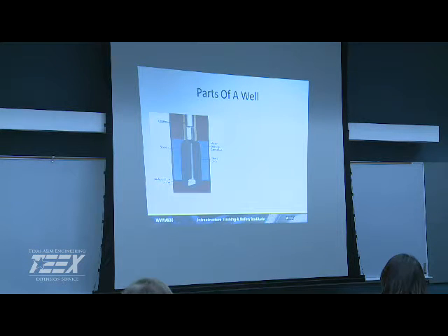We do need to have the casing sealed well. When we talk about wellhead protection, we got to not only protect on the surface of the ground, but we also need to make sure that our casing is intact, is sealed properly, things like that. And of course, in some areas you can have a couple hundred foot of screening, depending on how big your aquifer is, how big your pumps are, how much money you have.